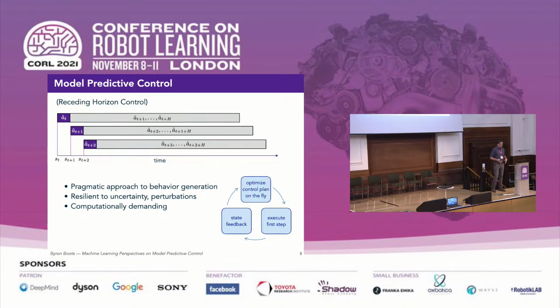Okay, so the horizon is always extending out h time steps in front of where we are, so h time steps into the future. And note that we're constantly using feedback, so we're re-estimating where we are in the world, we're re-estimating our state. And this feedback allows us to, at each time step, minimize this expected future cost in simulation while the robot is running.